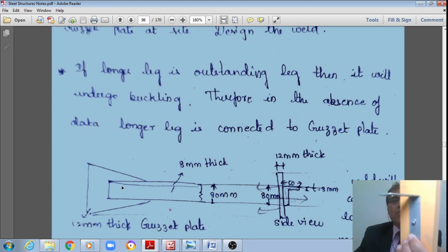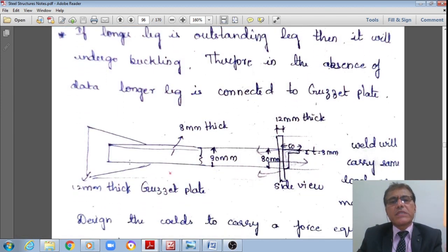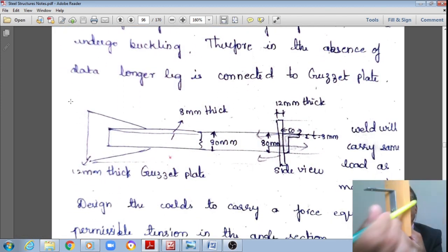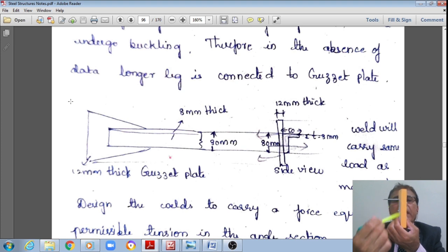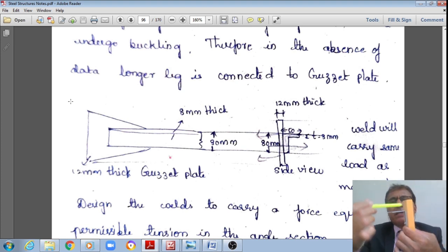Actual photograph, depiction, student, right? Whereas the same is now shown schematically like this, right? These are the gusset plate, right? Angle, right? Front view as well as the side view. That of the side view, right? Side view angle, right? This depth is equal to 80 mm. This depth is equal to 80 mm. Whereas this outstand is equal to 50 mm.